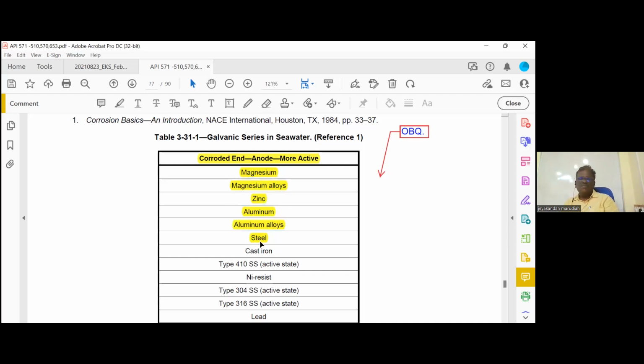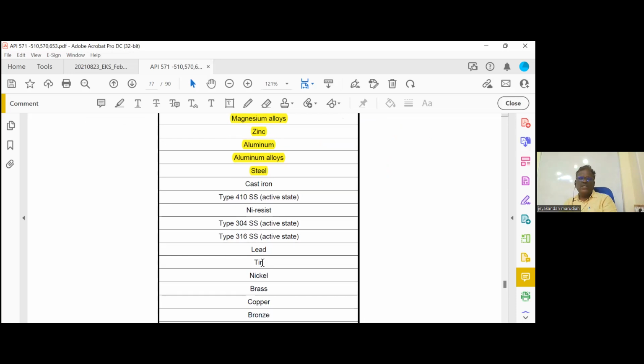The reason is whichever materials are farther apart in the table, the protection will be more. For example, when you combine lead and tin or lead and brass, there will be more effect, more protection, because of the distance between the two metals in the series. So this is called galvanic corrosion. How do we avoid galvanic corrosion? Design. If you work practically with stainless steel pipe, they will not allow direct contact with carbon steel structures. They will keep some spaces, even wooden planks, because of the galvanic corrosion problem. Different materials should not be allowed to be in contact.